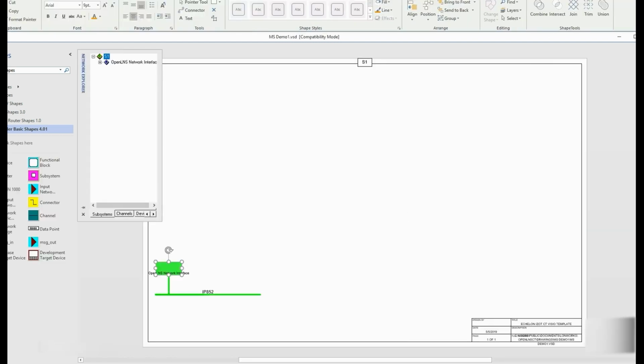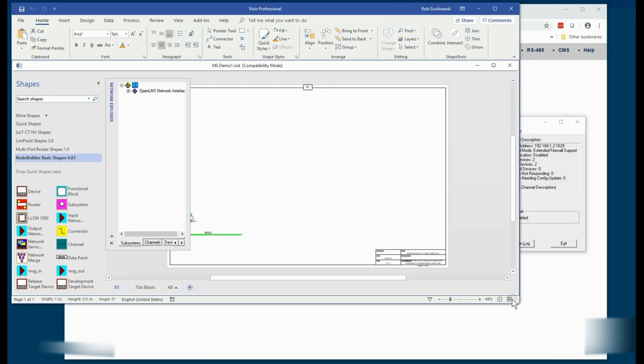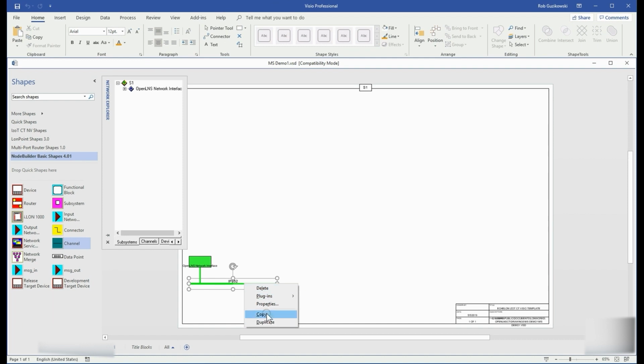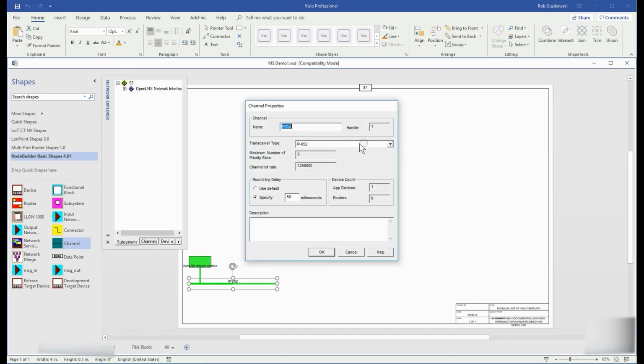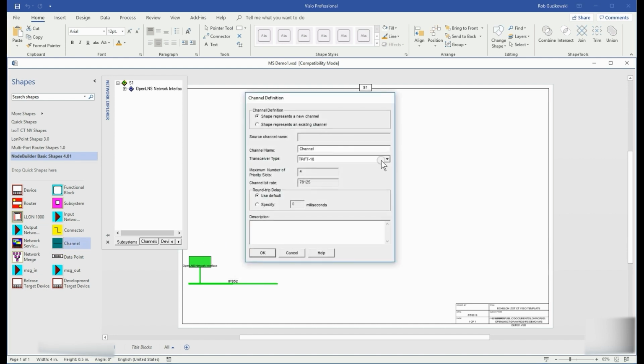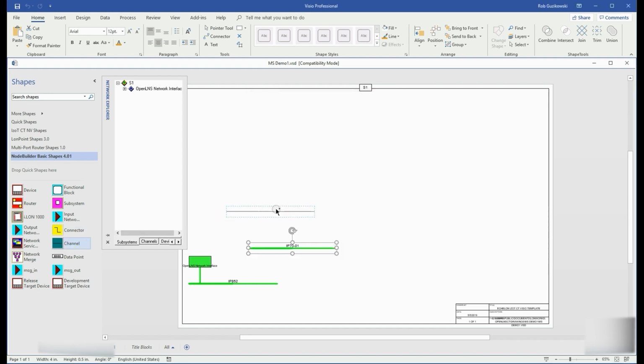First, we start building out the channels that we will use in our system. Verify that the backbone channel is configured to be IP852. If not, set it this way. Next, we need to define an internal channel IP70 that is used to route between IP852 and any of the 1 to 4 network interfaces that may be attached to the SmartServer IoT.